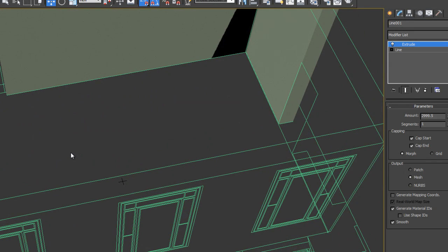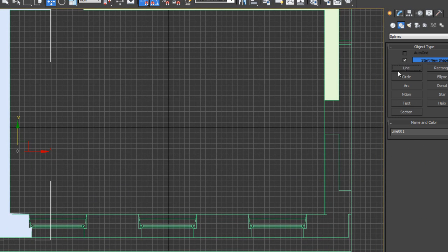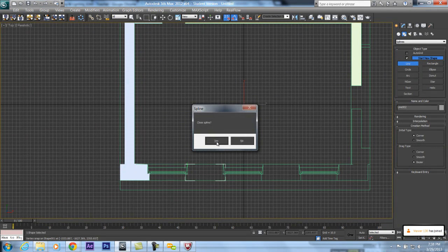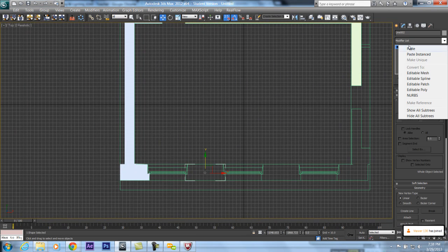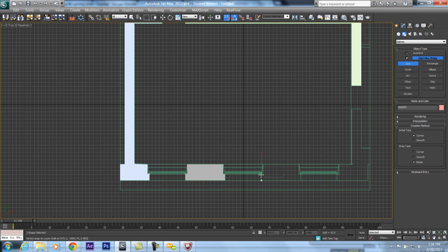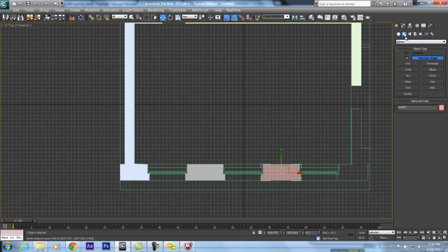Okay. Going back, I'm going to keep modeling this room, which is pretty fast, pretty easy. Same method: snapping with the 2.5 option tool to the vertices, and pasting the extrude modifier to those guys here. Which is a pretty fast and easy method.